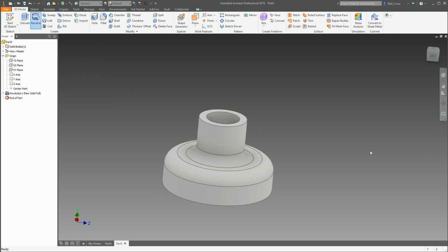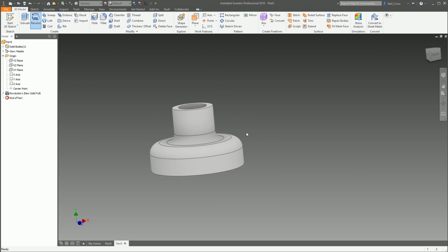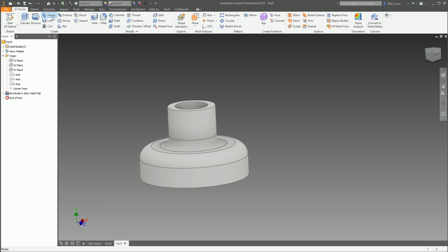And then there's your revolve. And you can imagine you can do all kinds of funky shapes with that. So that's kind of good. Sweep. Sweep is like an extrude, but whereas extrude takes a flat profile and extrudes it just up or down or mid-plane, it's kind of normal to the sketch. It just goes up or down from the sketch plane and then gives you a solid.